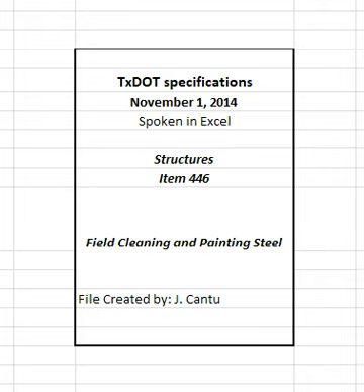Prepare all unpainted areas with abrasive blast cleaning. Repair primer coat and apply remaining coats after erection and maintenance work is complete. Prevent paint and overspray from coming in contact with passing traffic, private and public property, and areas of the bridge not designated to be painted. 4.7 Cleaning and painting existing steel.